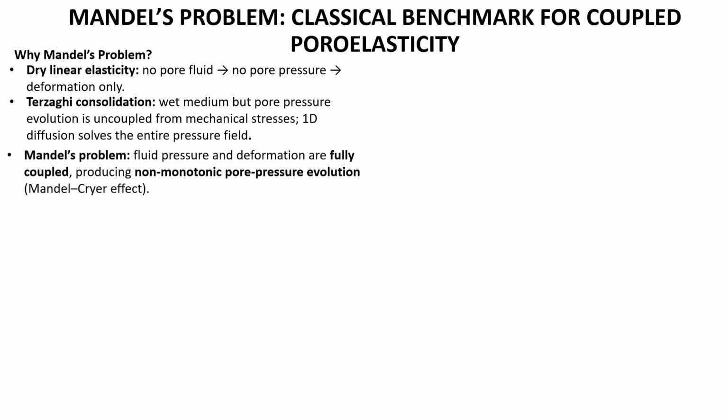However, the Mandel's problem introduces full coupling. Pore pressure affects deformation. Deformation feeds back into pressure. And all together, they produce a non-monotonic pore pressure evolution known as the Mandel-Cryer effect. This is one of the signature behaviors of poroelasticity in reservoir formations.